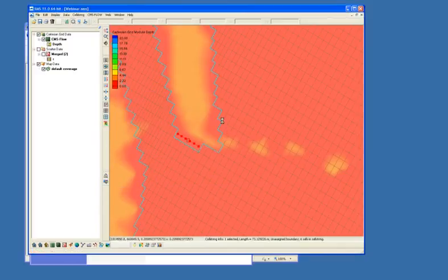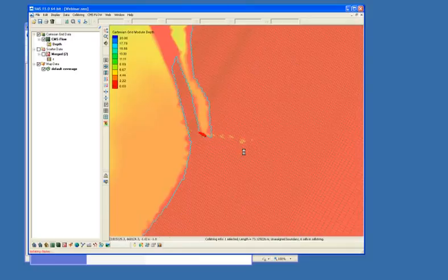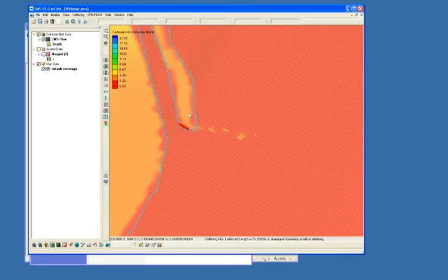So basically that's how you bring in any kind of external forcing from the outside of your domain. So the water would be coming in through this open boundary, being forced as water surface elevation, and then from this land boundary it would be coming in forced as a river flow.